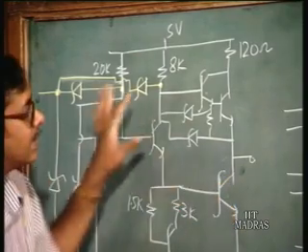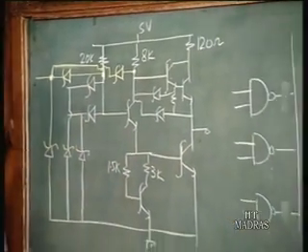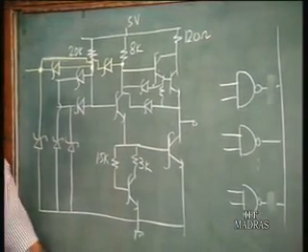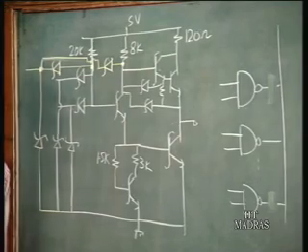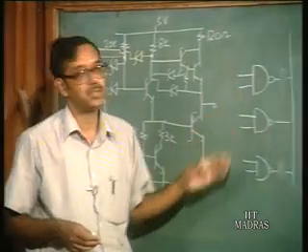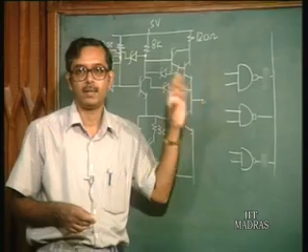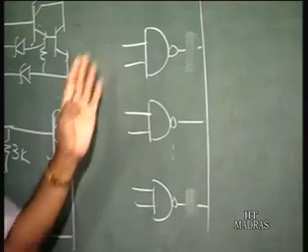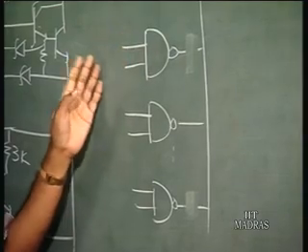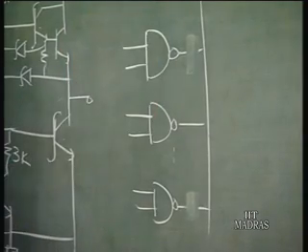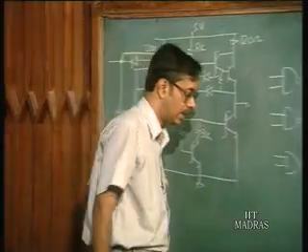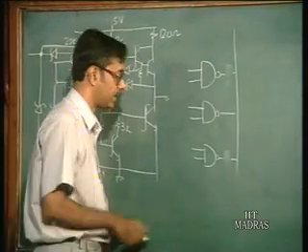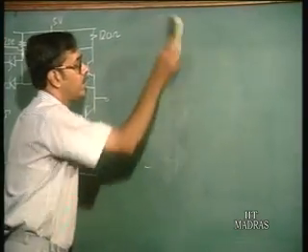So, this is another variation. This type of gates are also available in the TTL series. These are used as buffers, where you can either connect or disconnect the output of a particular circuit onto a common line. So, I just wanted to tell you this as a small variation of the normal TTL gates.